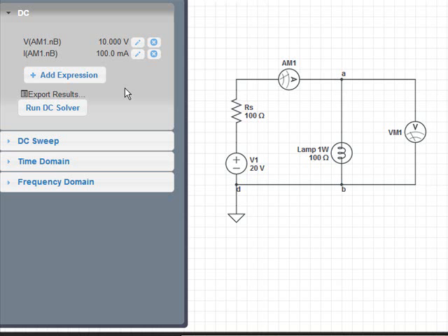Step 5, again, calculate power. This time, for step 5, you are calculating the power in the battery instead of the 10 volts that we are measuring, which is across the lamp. We are going to use 20 volts from the source. So 20 volts, and you still will use the same current because this is a series circuit, the current is the same in the circuit. Calculate the efficiency. Again, these formulas are found in the lab file.